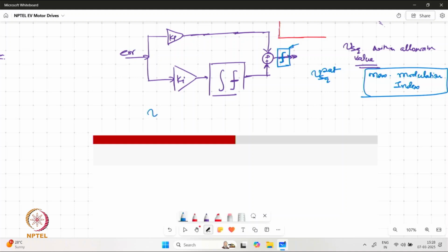So as we understand, our individual components VSD and VSQ, which are the components of the voltage vector, are going to have a magnitude which is 1.5 times the peak value of the individual phase quantity, which is why VSQ can be allowed to go up to that.